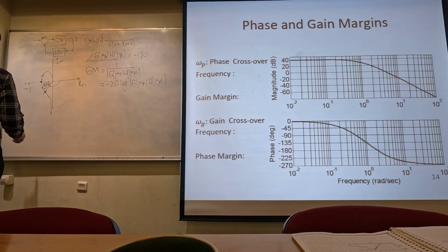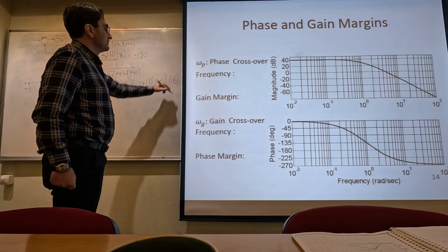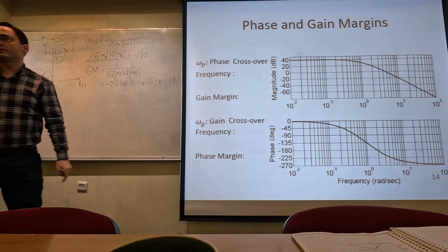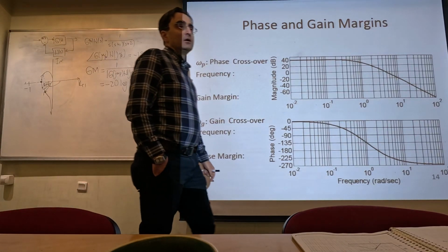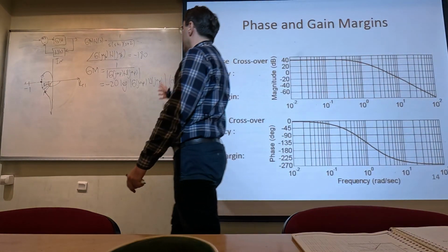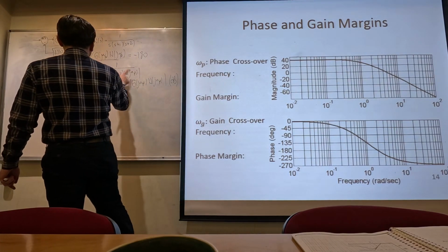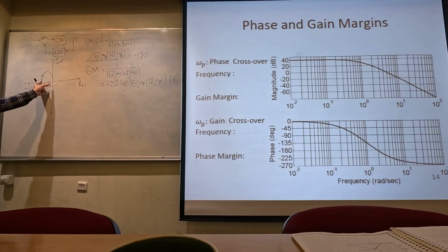This is called the gain margin in dB scale, and if it is positive, the closed loop system is stable. The more positive this quantity is, the more stable the closed loop system is. We need this quantity to be positive, meaning that the magnitude should be smaller than 1 for stability, because then there is no encirclement, and that gives us a closed loop stable system.